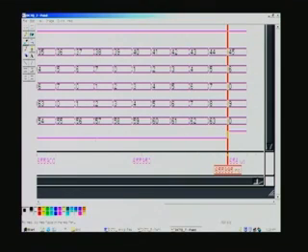See, at this point of time stop process goes high, which indicates all the 1024 blocks are processed. We started the processing at 635 nanoseconds, and now we are ending the process at 655995. So if you subtract the two, you will get 655360 nanoseconds. If you knock off that 0, you get it in clock cycles, that is 65536 clock cycles it has taken for 1024 blocks.